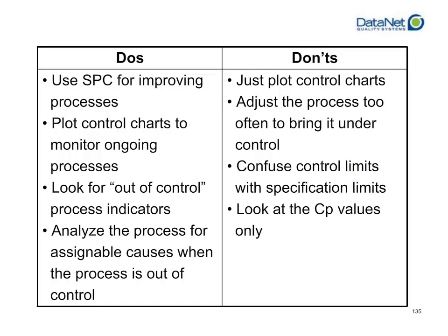Do not just look at a Cp value when you're doing a capability analysis. That only tells you if you're theoretically capable of producing within control. It doesn't necessarily tell you that you're producing anything within spec. You need to run Cp and Cpk, which is really easy to do when you're using a real-time software package like WinSPC, as opposed to doing things by hand.